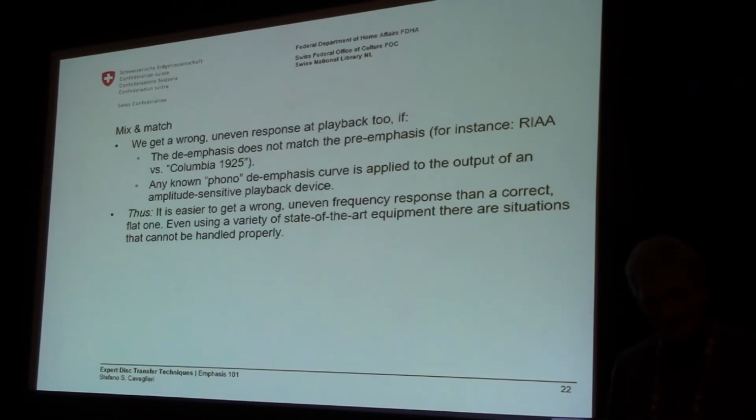We also get a wrong frequency spectrum if we apply any known phono or the traditional electrical de-emphasis curve to the output of an amplitude-sensitive playback device.